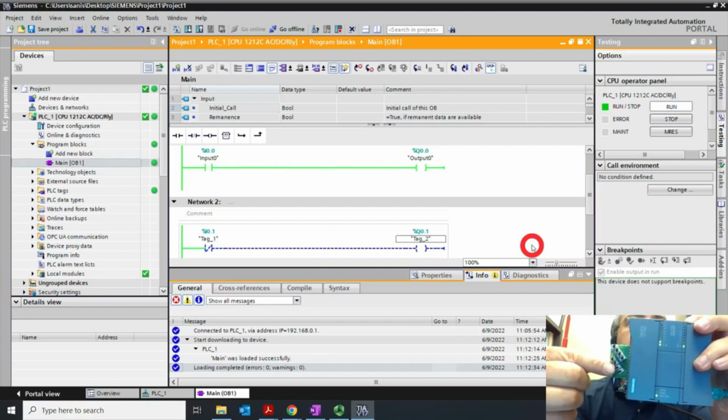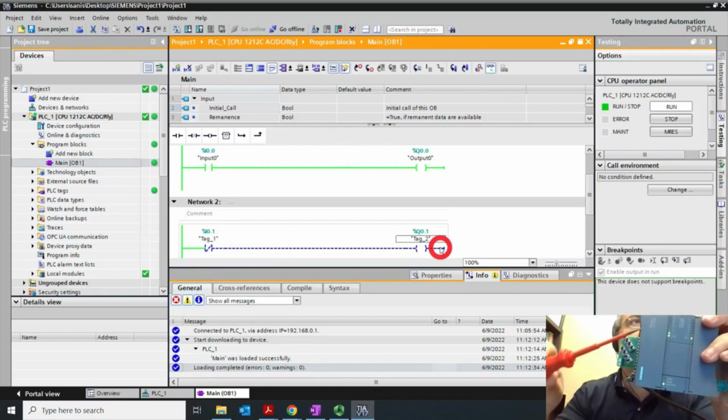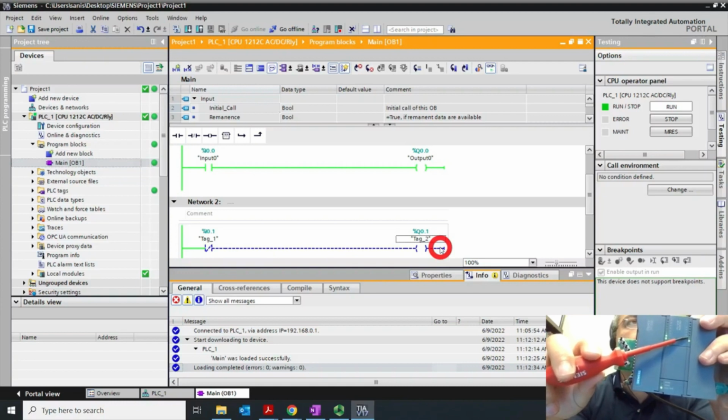So let's try the second ladder logic that we have. We already tested this one. Let's do this. You tell me, based off these LEDs that you see here, what's the value on the IO pins? IO1 is 1, right? So I have 1. What do you expect? If you have 1, this is normally closed. With 1, it should be open and the output should be 0. So even if you check the output, just be careful. Whatever is on here is output 0, which is the first program that we wrote. So output 1 is this one, which is actually off.